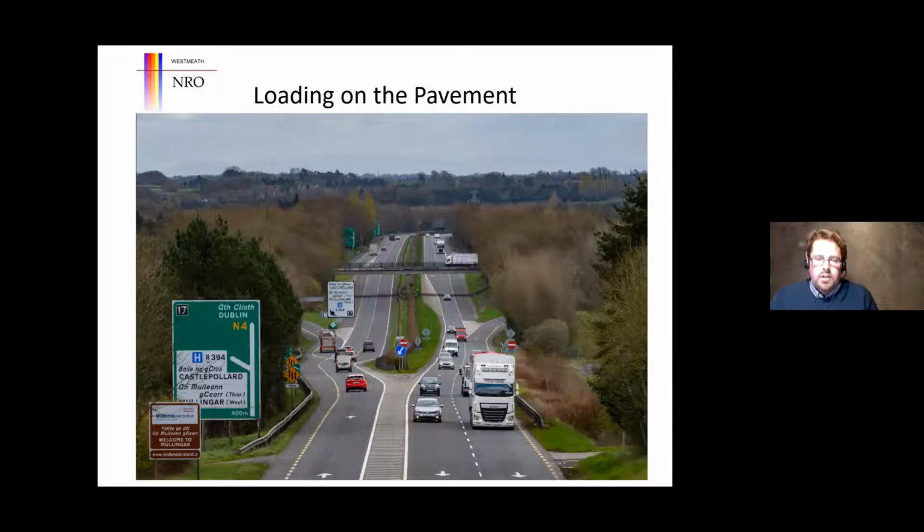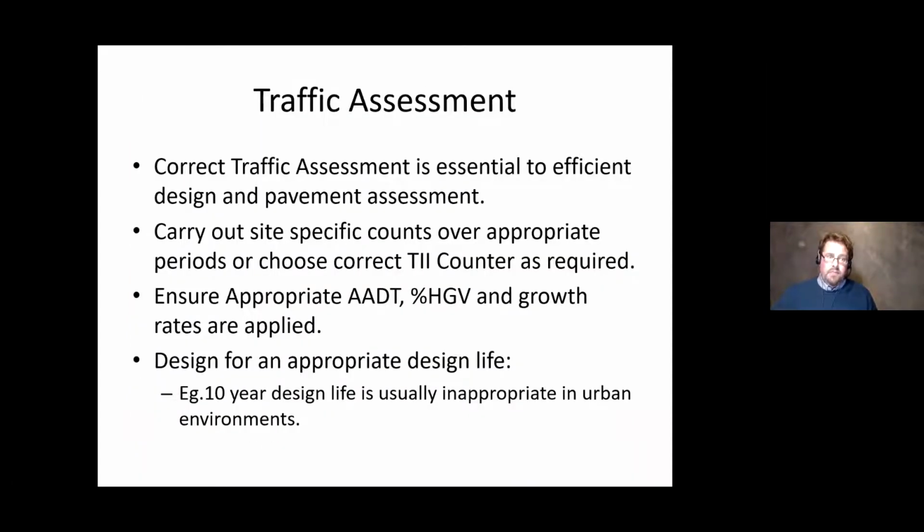So just be conscious that when you're giving your AADTs and percentage heavy goods vehicles, the percentage heavy goods vehicles is very important to have. These kind of speak for themselves, but the correct traffic assessment is essential for efficient design and pavement assessment.